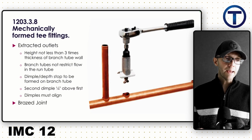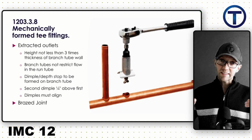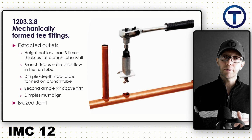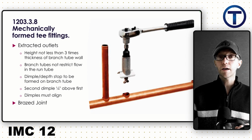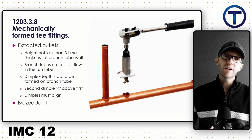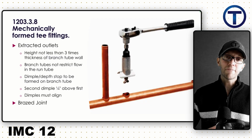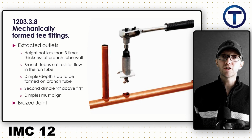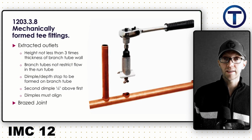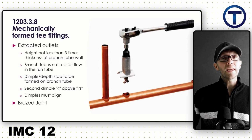A dimple and depth stop should be formed on the branch tube, so that's going to keep it from pushing down in too far. And the second dimple should be a 1/4 inch above the first. This helps me to see if I've pushed it in far enough for me to create a good joint. Then the dimples must align before this is brazed. This is going to be a brazed joint. This does not give enough of a connection for a solder joint. And like I say, I don't know that many people are doing this anymore, but it is in the code as an approved method.